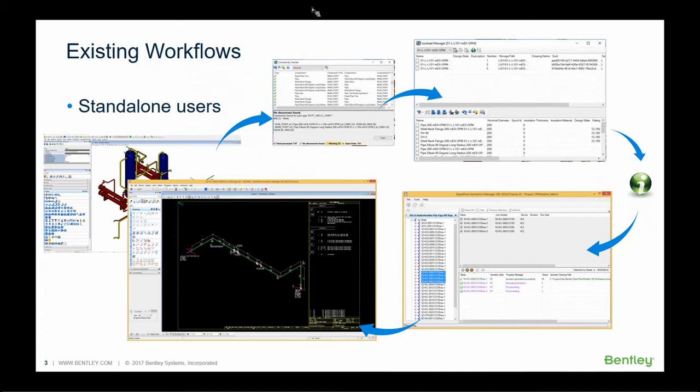When creating an ISO sheet from a pipeline, they could use various methods: creating stop signs, manually placing and selecting components and allocating them into different ISO sheets, or using auto generation of ISO sheets in Isometric Manager.